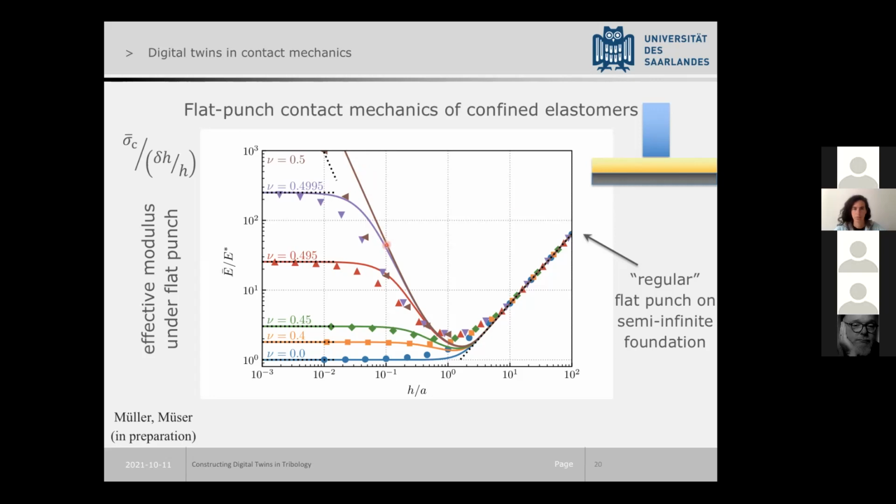And basically, this is due to the fact that if you have at least one sticking condition, when you start squeezing down the indenter, you are starting to see a little bit of the bulk modulus, right? And when you start to see the bulk modulus for an elastomer, you start to see something that is very, very stiff. And this is why you get a relative minimum here. And if you're running out of questions, you can ask me, what is the meaning of these drawn lines?